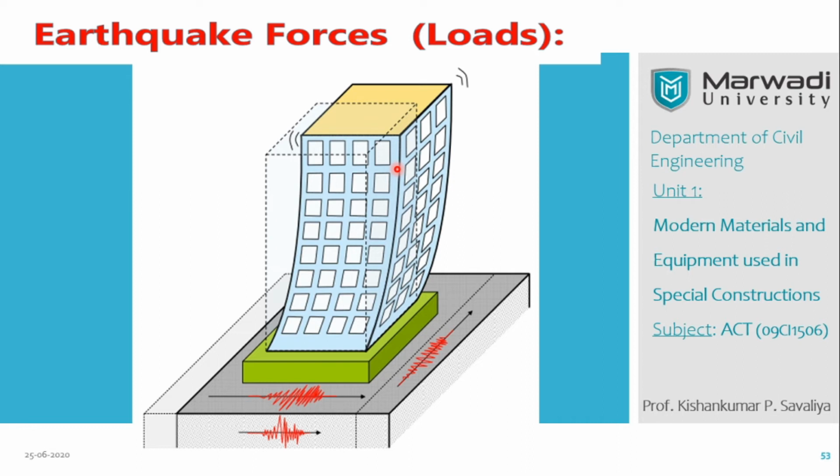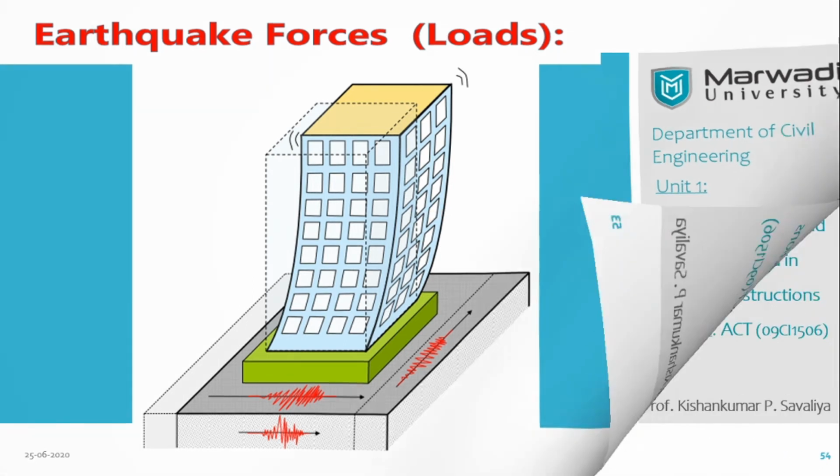Definitely you cannot see a movement like this in the real world; it is a relatively small effect. If you put sensors, 4 at the bottom, 4 at the top, and 4 at the midway, you will get an idea of how the building is moving during the earthquake. That kind of experiment we are already doing in our laboratories.